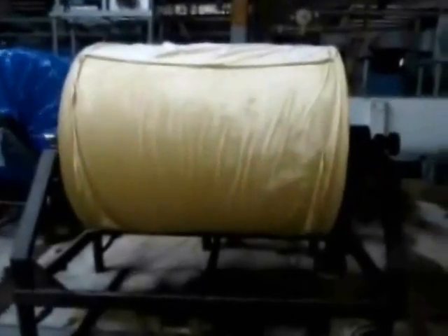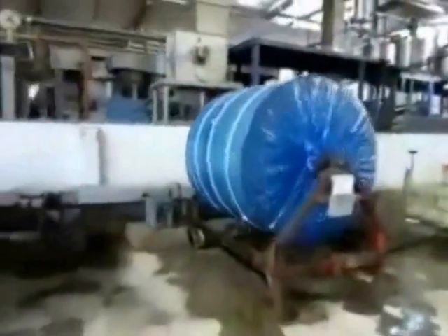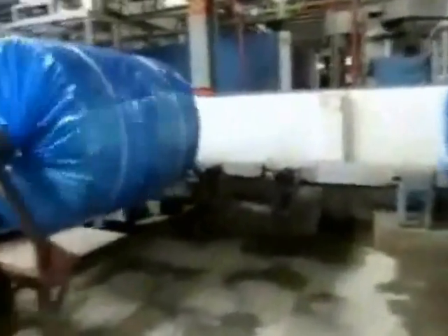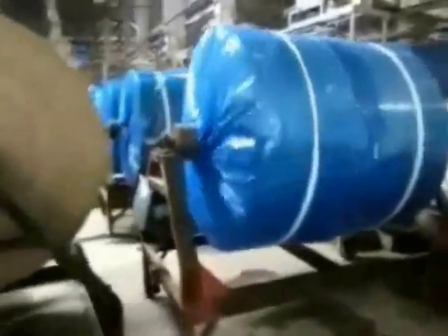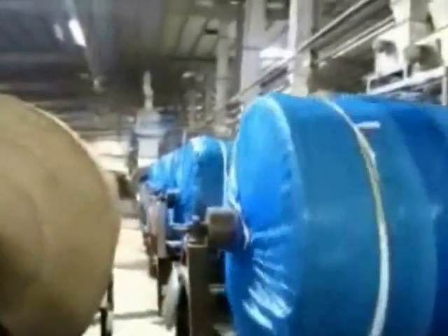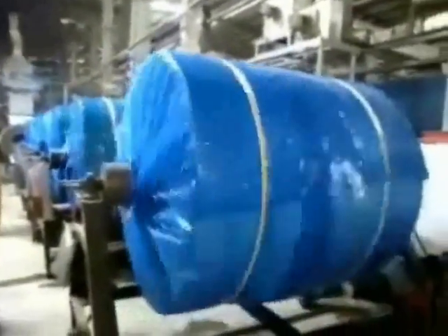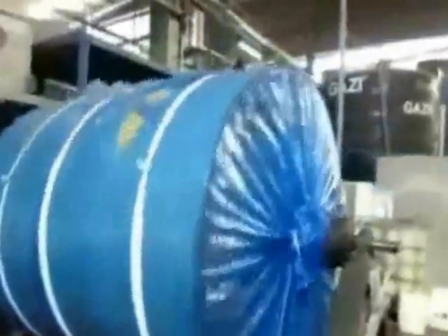Batching. It is also known as the conditioning of the fabric. After singeing or by polishing, the fabrics are allowed for conditioning with hydrochloric acid or sulfuric acid for 8 hours time duration, including a rotating motion where the fabrics are kept or packed with an airtight polythene. The conditioning time or chemicals are used according to the fabric or fiber composition.